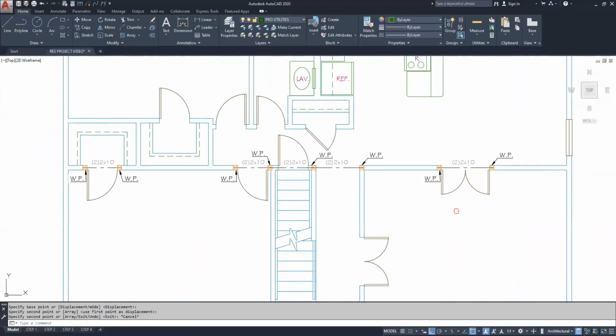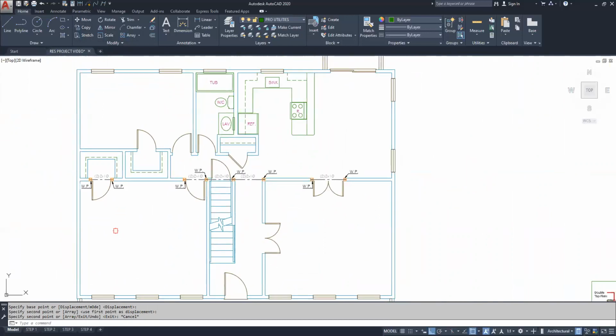All right, so we took care of that wall down the middle, known as the bearing wall. You might hear people talk about this when they're trying to remodel an existing house, existing building. Is this a bearing wall? And what does that mean? That means if I take that wall down, the house could potentially collapse. Honestly, it might not collapse at that second, but over time you might see the floors above sag and things start to go out of whack. It's really not a good practice to take out a bearing wall without putting a header in.